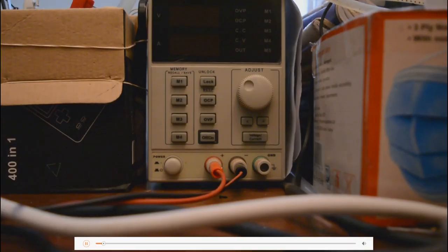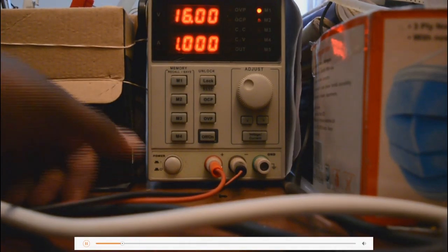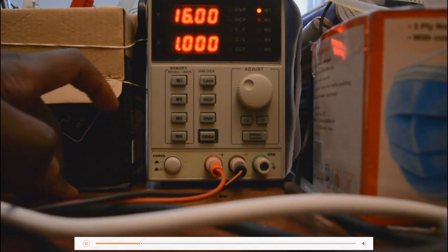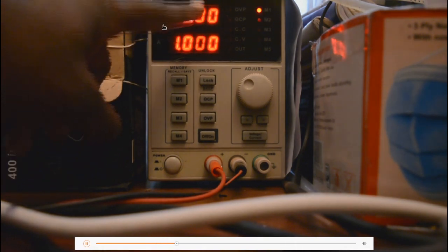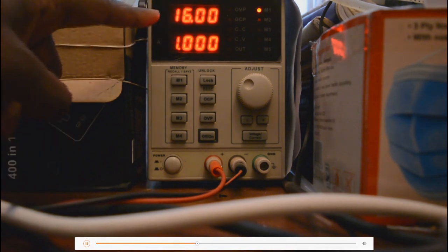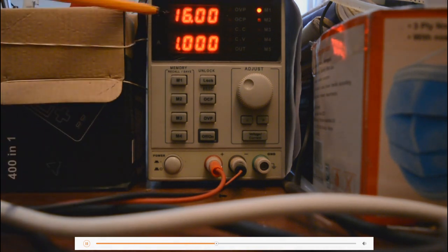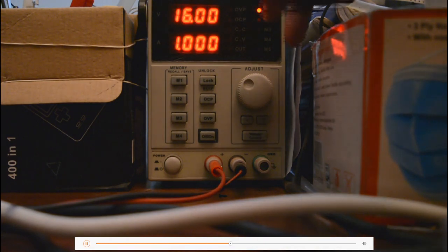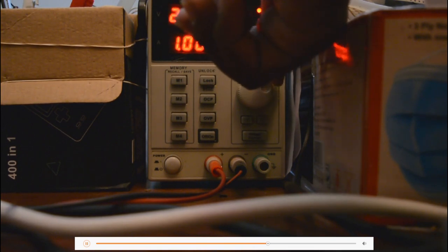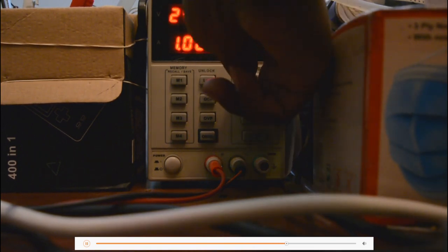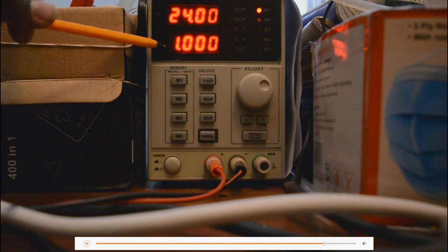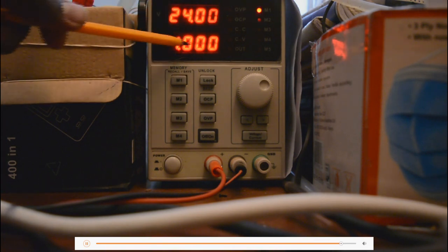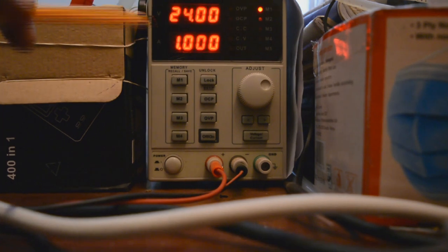So now we are going to power our board using a desktop power supply, and as per what we had read in the starting, always make sure the voltage is correct. We had agreed that we need 24 volts applied so that the PLC can switch and control the outputs that we have. So now I'm going to set the voltage correctly to 24 volts, and I'm going to set the maximum current to 1 ampere so that the power supply can give this power to the PLC to work correctly.